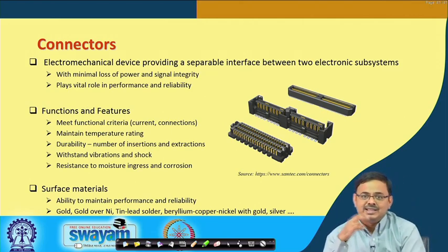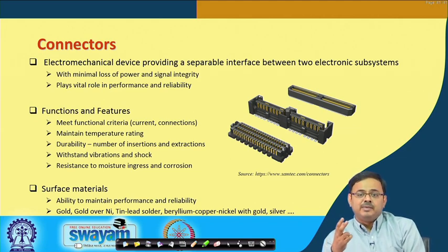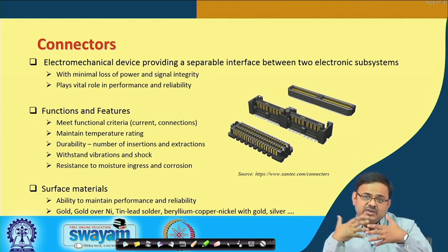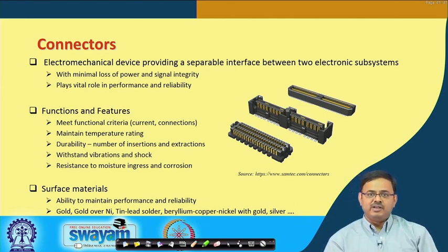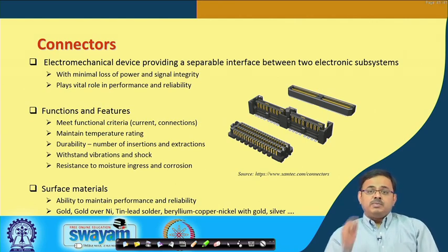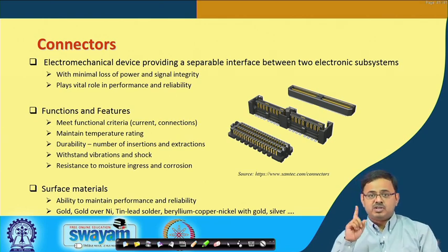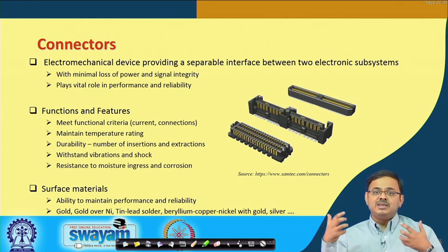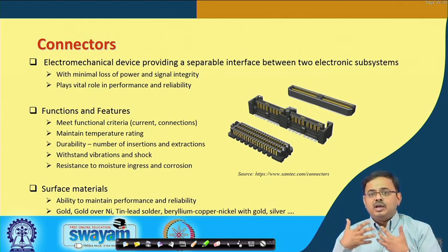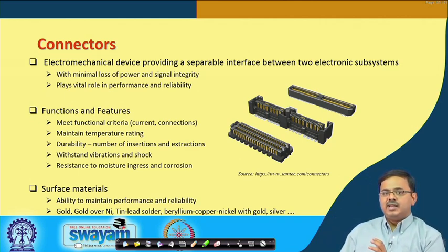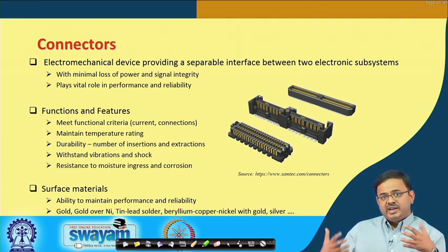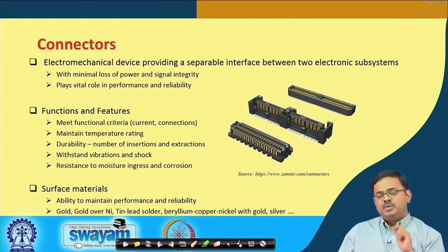So, it does play a role, the signal integrity, the purity of the signal as well as the integrity of the signal that gets transmitted from subsystem 1 to subsystem 2 through this connector needs to be maintained very well. So, it plays a vital role not just in performance, but also in reliability. Why is it important? Because remember the word separable, this is removable, detachable. So, the connector should be designed so that it can be detached multiple times, right. So, every time I attach and detach, I should not be losing performance,